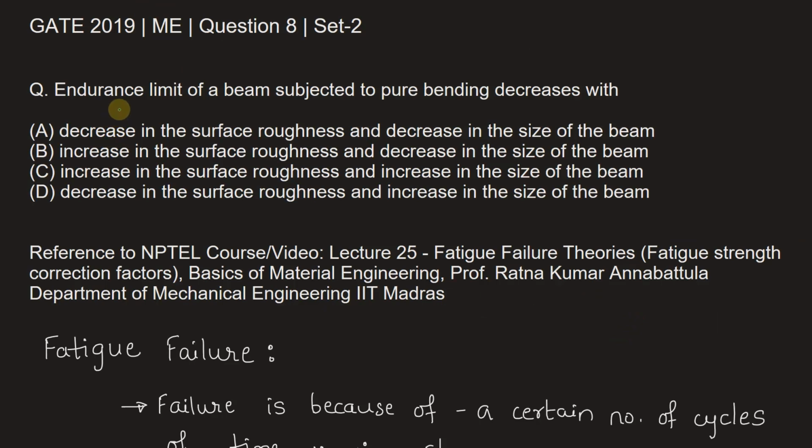So the answer for this particular question is: the endurance limit of a beam subjected to pure bending decreases with an increase in surface roughness as well as an increase in the size of the beam. So it is option C.